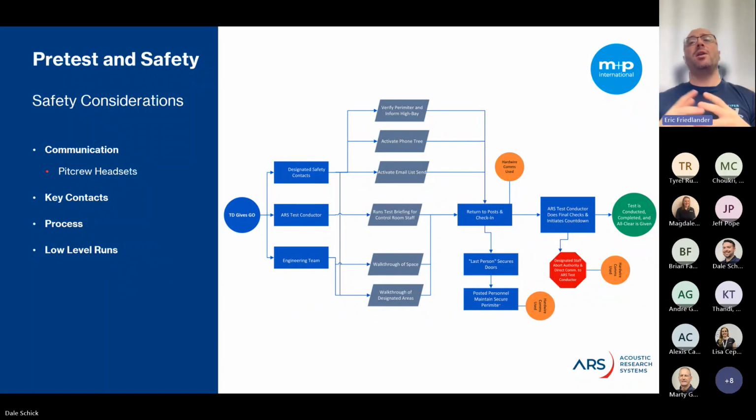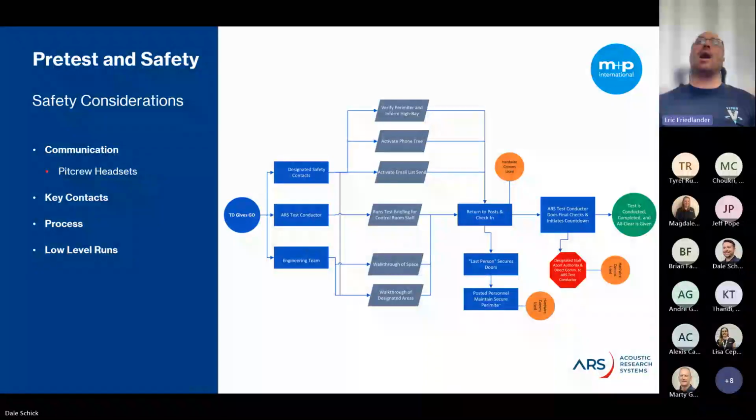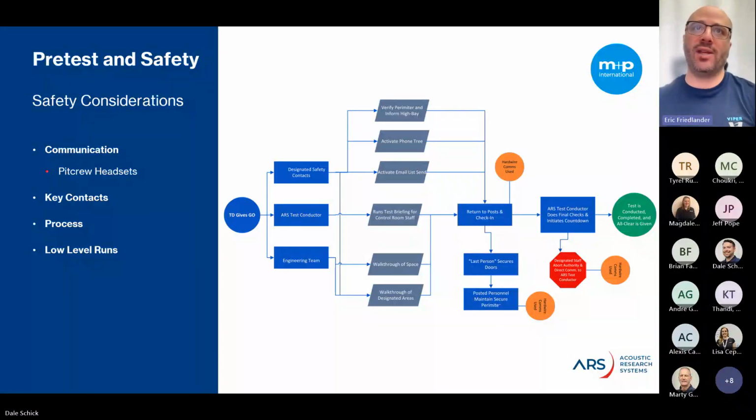Another thing to consider is you've got a couple of people on headset, while your test conductor and operator might be off headset, with the conductor sitting next to him. You're going to have a certain number of people who are authorized to call an abort. So if they see something wrong, something anomalous from a safety standpoint outside of the actual acoustic test, they can call an abort per the customer's test director. We also have a manual handheld abort switch that somebody can hold and fire, and that will shut down all the amplifiers instantaneously and bring everything to a quick ramp down. And then ideally, we get through the run, we're clear, and then we give the all clear on the headset. So there are several different ways to handle that.